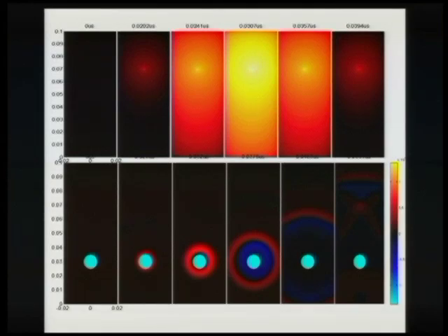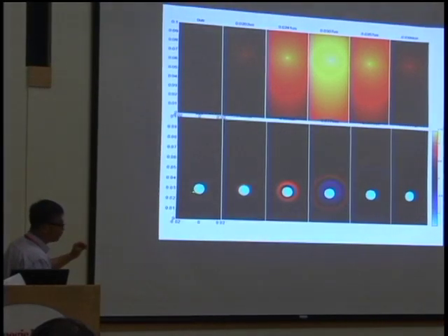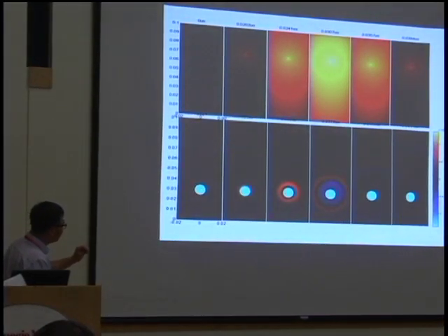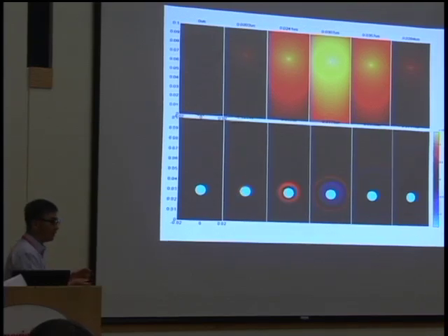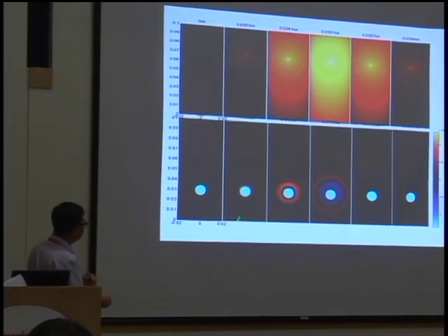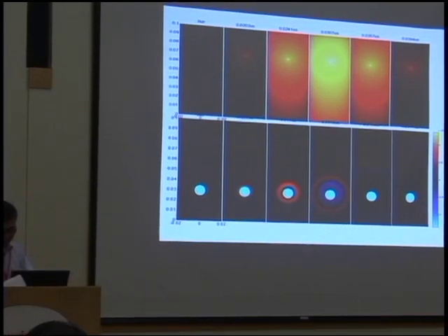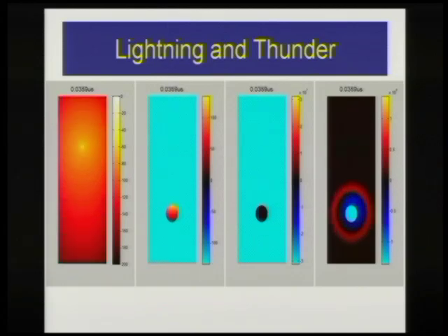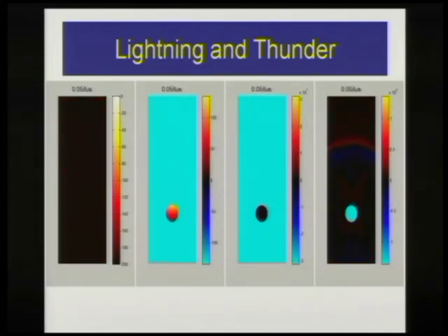So this is an FE-based simulation we did. The top part is the laser source, and the laser goes by and is exposed to the target, where it will be absorbed, and then it starts generating. This is the light source in red, and blue is the wavefront that generates sound. So the energy source to detect is light, and then we forget about light and listen to the ultrasound.